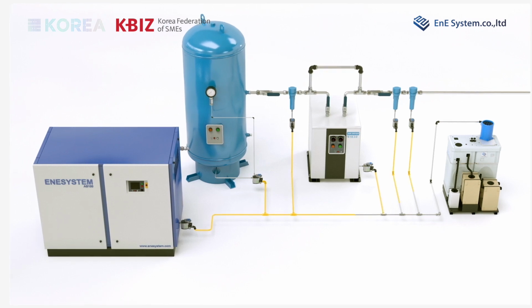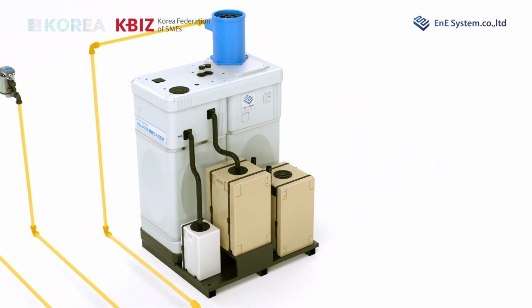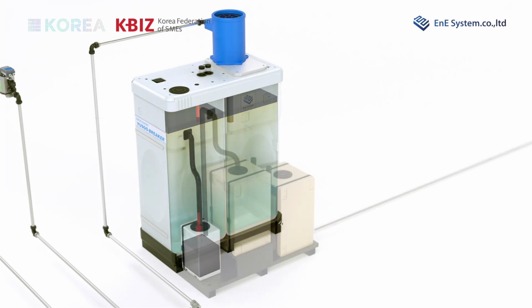The oil-water separator brings oil-contaminated condensate to a pressure relief chamber, which removes pressure. First, oil is separated from the collected condensate by means of gravity separation from the pre-tank, and the floated oil is discharged through the oil drain line. Emulsified condensate is filtered out through several filtering steps and purified before being discharged.